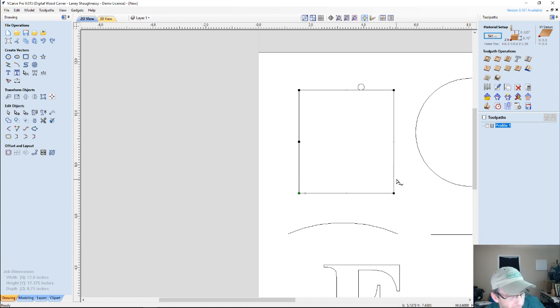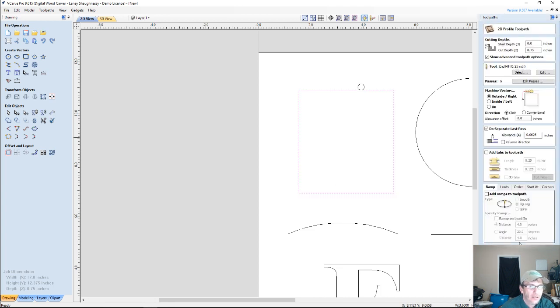And how do I guarantee that the project will start at the start point? Well, that is in our advanced options here. In our advanced options, and it doesn't matter, even if we're doing pocket cuts and things like that, we always have the Start At tab. So we could keep the current start points, or we could optimize the start points.